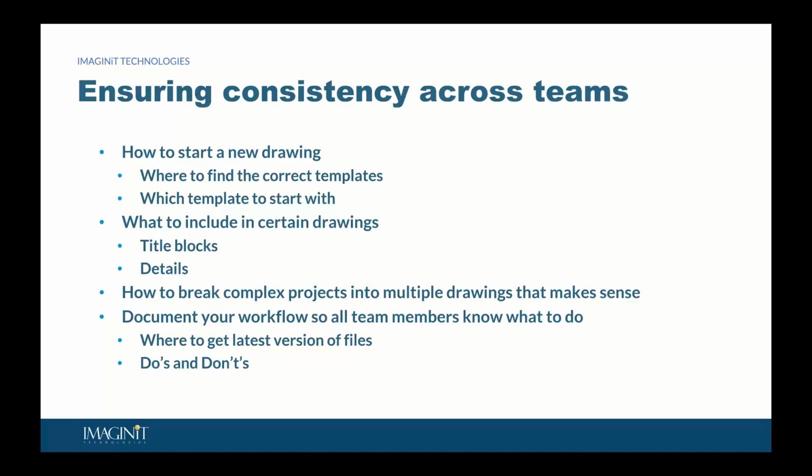Where can you break a complex project, or where can you break a surface down into multiple pieces, if you start getting those MMS files or the other files that get created when your surface exceeds the point count? If you're dealing with a DTM surface, a DEM surface, a digital elevation model, as soon as your points exceed 1 million, it'll create that external file that needs to follow that Civil 3D drawing in order to have your surface. If you're just doing standard ground shots, it's 2 million.